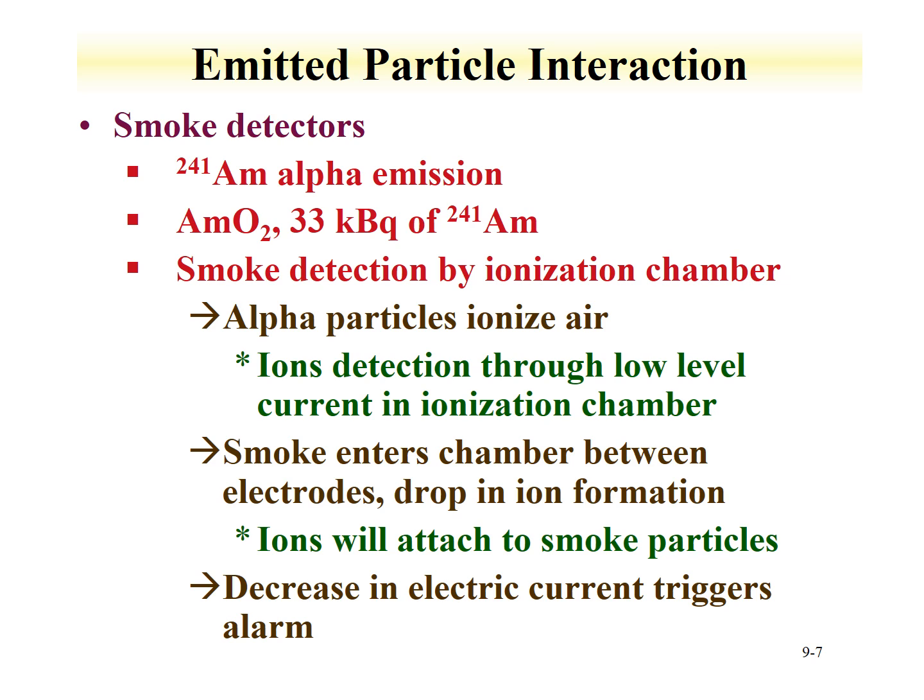So basically, smoke enters an ionization chamber through this route. When smoke is not present, alpha particles ionize air in the ionization chamber. These ions travel in the chamber and create a low current, which is detected.